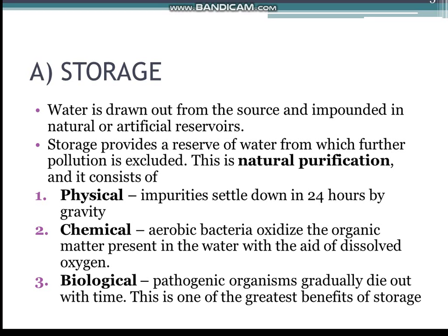First, physical. By mere storage, the quality of water improves. About 90% of the suspended impurities settle down in 24 hours by gravity. The water becomes clearer. This allows penetration of light and reduces the work of the filters.